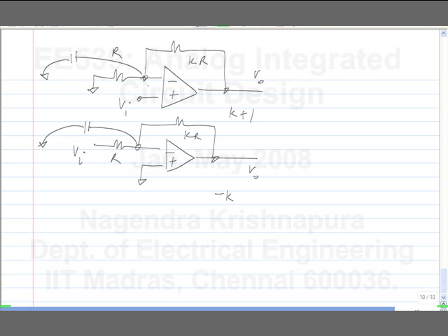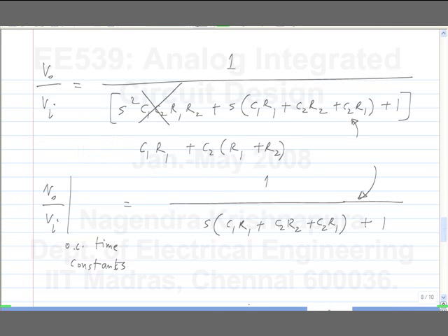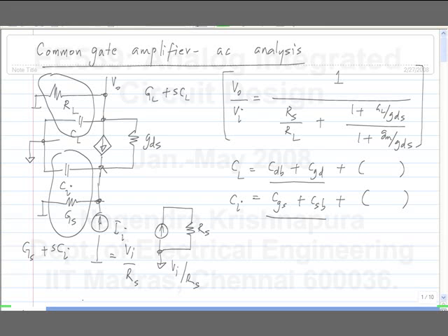First of all, the DC gain does not have a negative sign, so there is not much motivation to put feedback around it. At least it's not a negative feedback system. It's more like positive feedback, except that any resistance you connect also influences the gain itself. How it influences the gain can be easily seen if we have the expression for the gain here. Any additional resistance you connect across GDS, or in general any impedance, I will call it uppercase GDS, you simply add it to GDS.